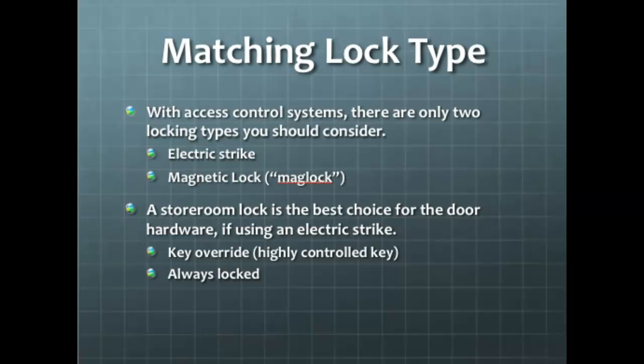You as the security manager can take normally the master key, or even something higher than that that's off the master key system, over to that door and turn it so that the handle turns. And instead of the door frame device, the electric strike, retracting, the actual bolt on the door comes back, right? So there are two ways to operate those.